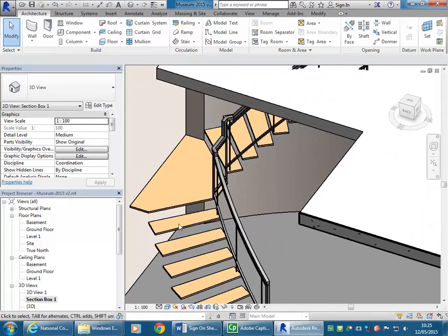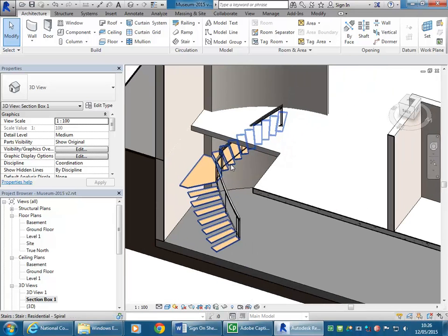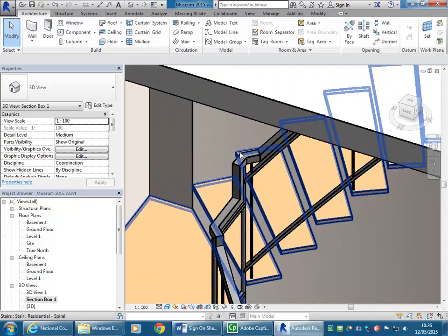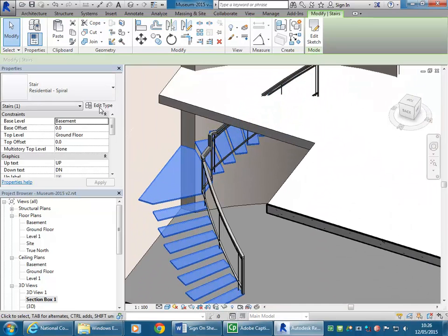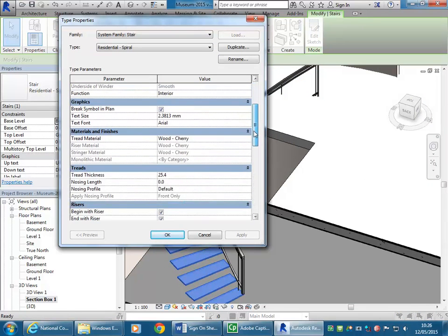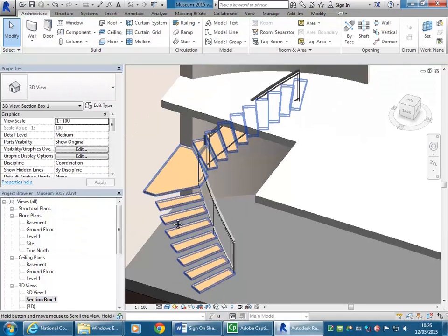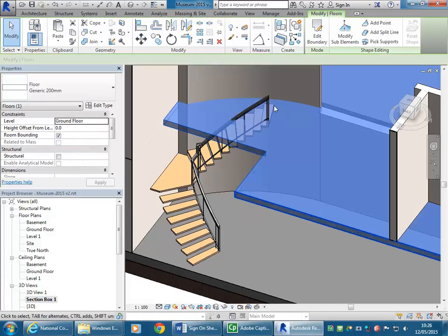So remember, because the stair doesn't have a stringer, it's got to be cantilevered out from a wall. It couldn't be freestanding, this stair. So that's a cantilevered stair, which is, in other words, projecting out from the wall. And if it is a true cantilevered stair, it would probably need to have a thicker tread. So instead of 25mm, I'd make that at least about 50. And then also remember, the floor needs to be adjusted to follow the shape of your stair.